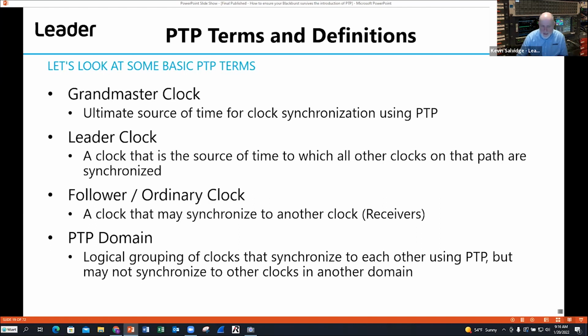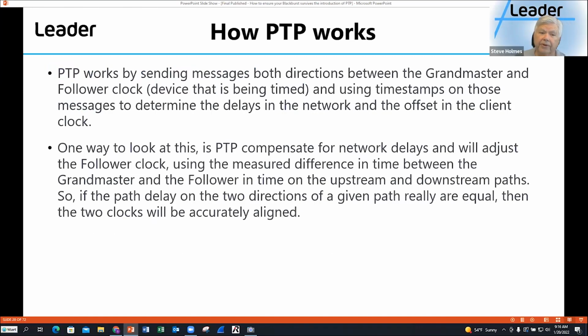You alluded to it earlier, and I've heard consultants say there isn't such a thing as an emergency changeover unit when it comes to PTP sources. Is that correct? How do they work? How do they know who's the Grand Master? You are absolutely correct, Kevin. There is no ECO per se in a PTP network.